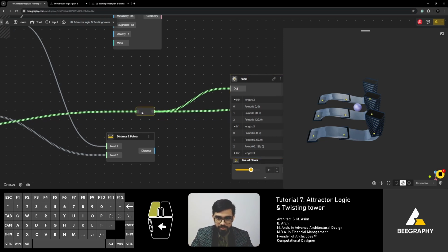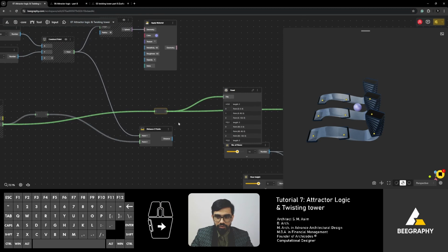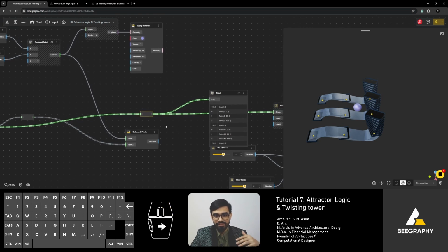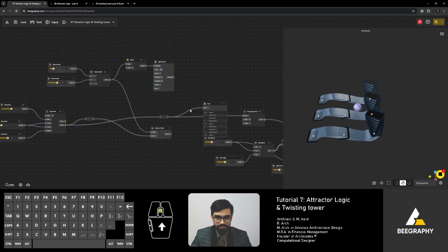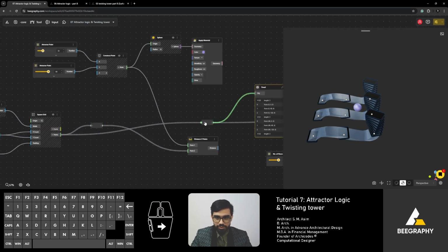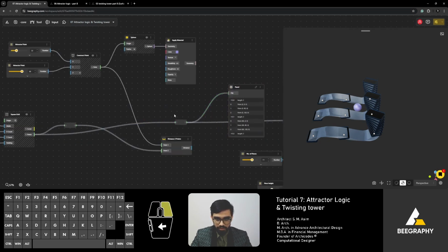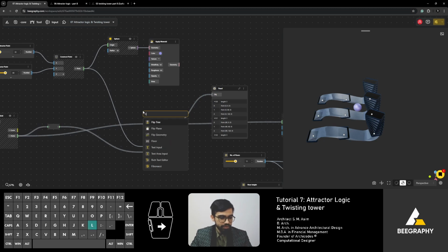So it's a very simple solution. We are going to flatten so that all of these points become one long list of 9 points, and then for each of them we'll put them into a branch. If you remember, we had already accidentally done this and then we had reversed it. So let me show you what I mean. So there is flatten tree.